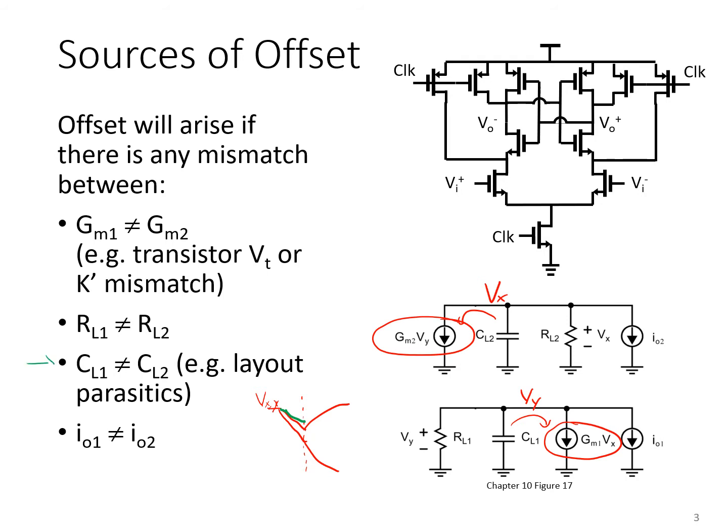Another possibility is that the transconductors, GM1, GM2, may not be the same. Again, this can arise because of many kinds of mismatches in the schematic above. Again, the larger GM will have an advantage in the race to the bottom. And finally, any small signal resistances that show up in each half circuit will also create differences in time constants between these two nodes that can give one side an advantage in the race.